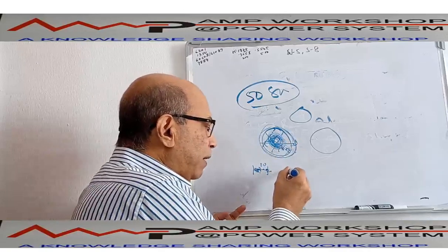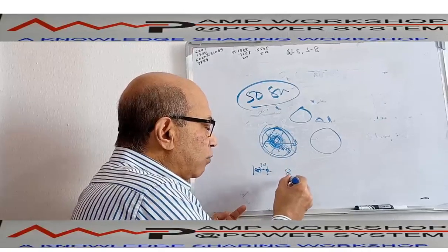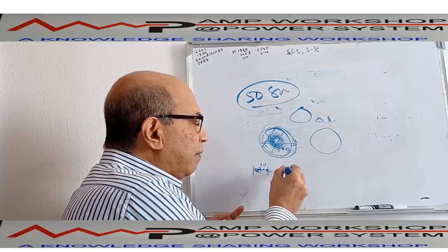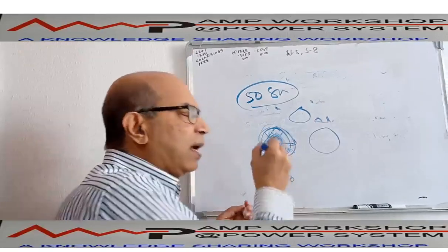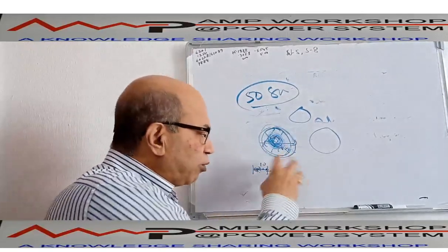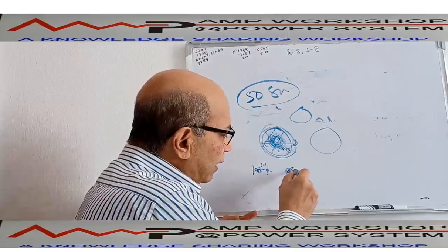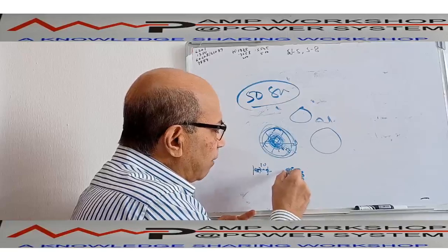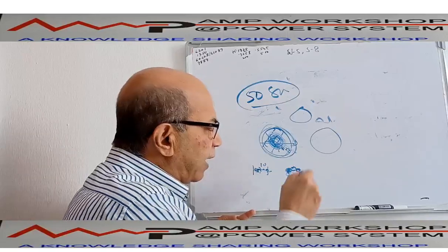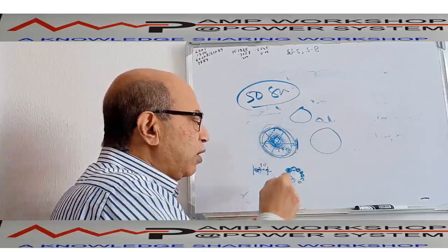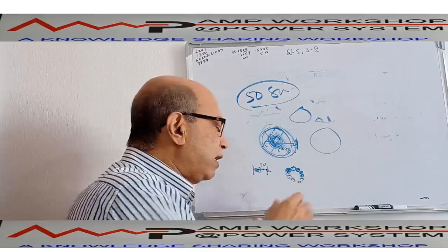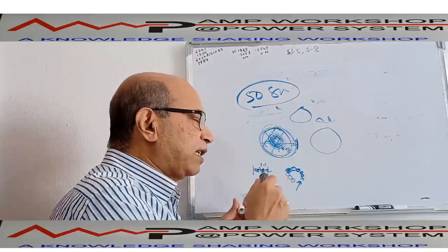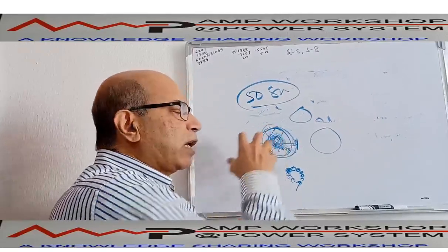In that case, what will happen? These wires will be of smaller diameter. With a smaller diameter, the center area will not carry any current, but the surface area will. The effective current carrying area will be increased by this process, because now, instead of one, there are multiple conductors. In all the conductors the center point does not carry current, but the surface does, and if we add up all the surfaces, it will be more than this single surface area. This is called a strand. Each strand has some diameter, so by splitting the diameter, we can make the total conductor.